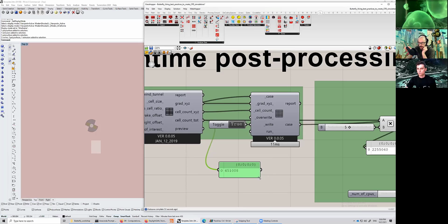I should say that for 1 million cells, you should have a bit over 1 gigabyte of memory. It's a very, very plain rule of thumb. If you want to run a 10 million cell simulation, I would have at least 16 or 12, because you also have Windows or Linux where you run it. You have other things running. So the rough rule of thumb is 1 million cells, 1 gigabyte. Which is okay today. Most of us have a lot of memory, but if you're doing this on a laptop, just bear in mind that maybe you have some restrictions.